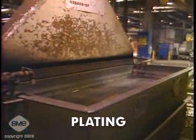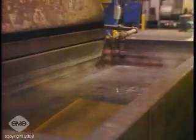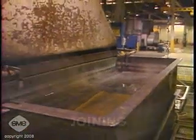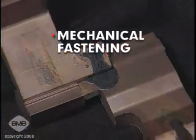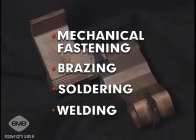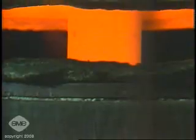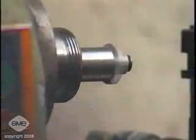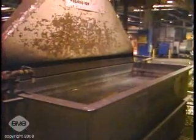Conventional plating methods can be used on powder metal parts, but porous parts must be sealed first to provide non-porous surfaces and prevent entrapment of plating solutions. Joining processes include mechanical fastening, brazing, soldering, and numerous welding methods. Most of these secondary operations are also applicable to powder metal parts made by injection molding or isostatic pressing.